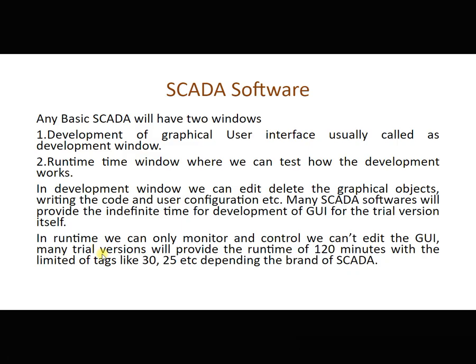So license, in the sense, you will be purchasing your SCADA based on the number of tags you can create. Tags in the sense will be representing your IOs only. Like 32 or 64 or 128 tags, this is what you are going to define. If you don't have a license, you can go with the demo version.